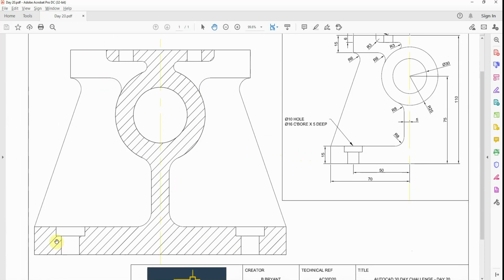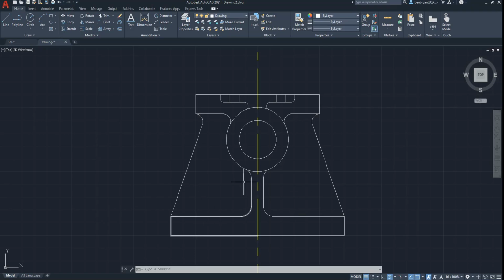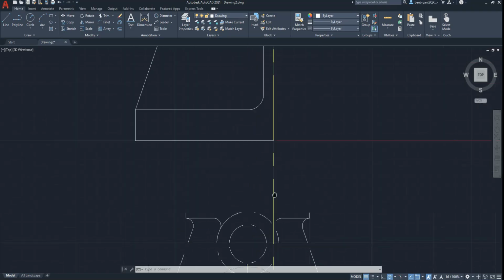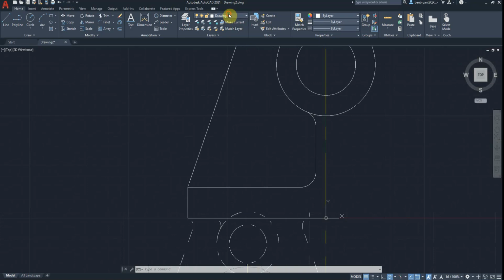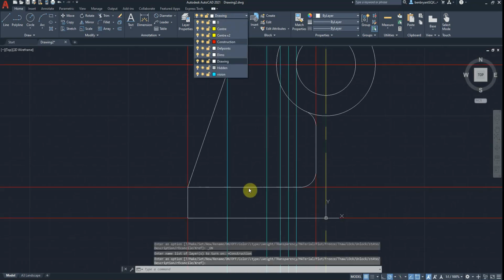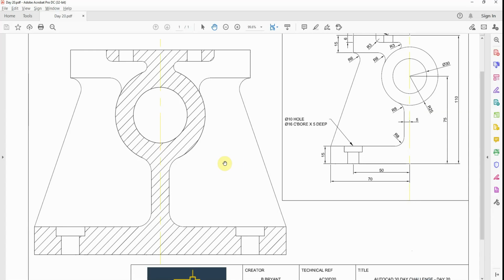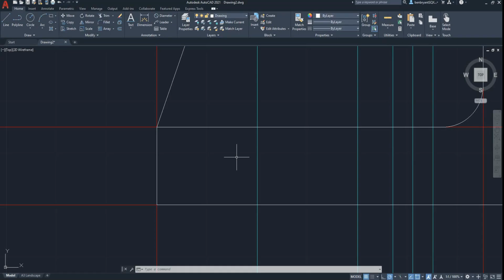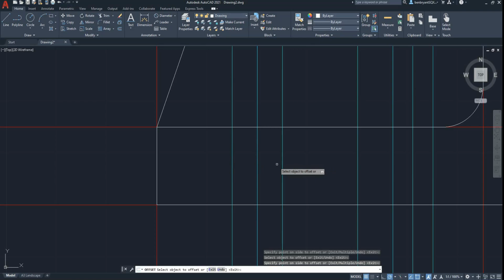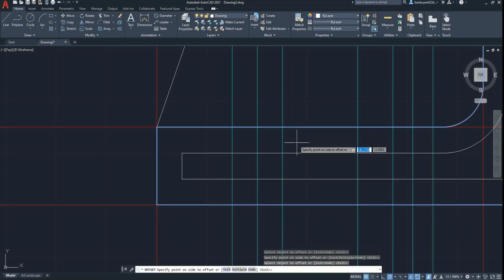Okay, so that's now both sides of my side done. Now what I want to do is, I haven't put in a counterbore. So I haven't put in the counterbores on that lower side. So what I'm going to do is come up to this section now, put my construction lines back on, and the counterbore is based around this blue line here. So it's the 50 line, so it's 16, okay, and then a 10. So I'm going to offset 5 either side. Okay, it's dropping down 5 deep, so 5 coming down.